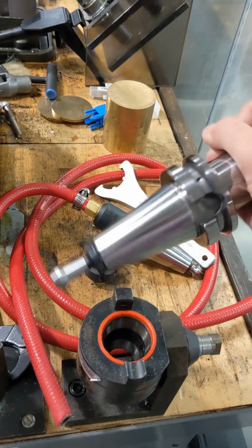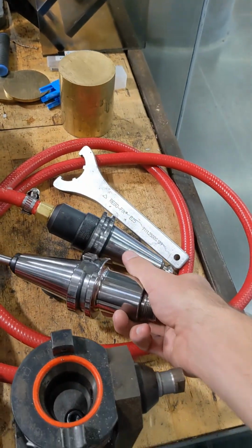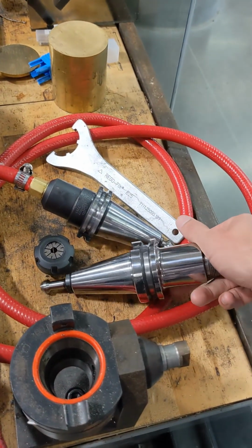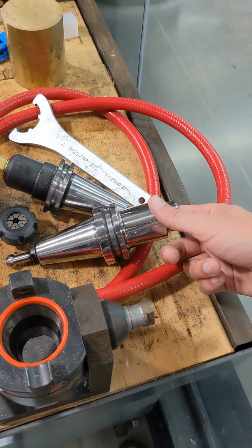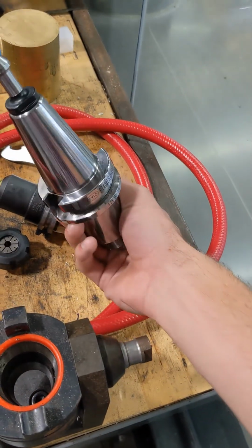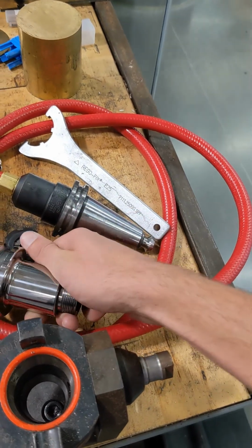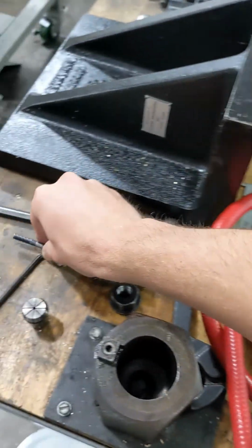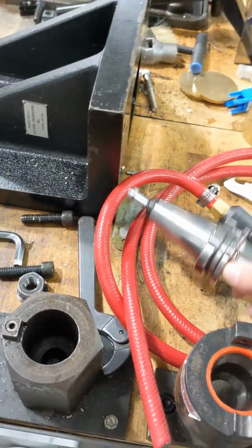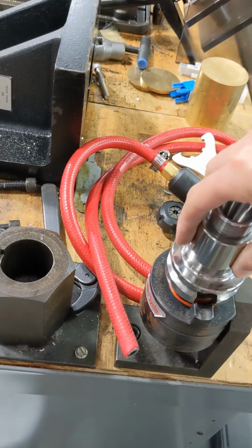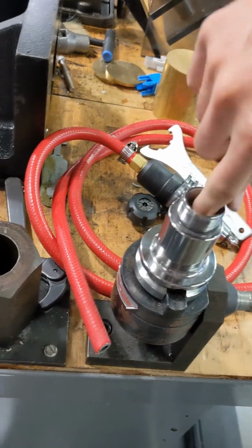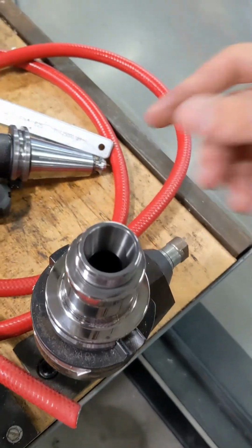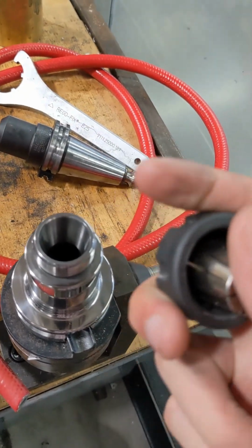So I'm going to pull our end mill out of our tool holder very carefully here, if I can find it. Okay, there's our end mill. We're going to put this in a safe place because that's a very nice end mill. I'm going to put our tool holder back in here. We want to clean out the bore so it's got no chips or anything on the inside of it. We can blow it out with air if that would be helpful.